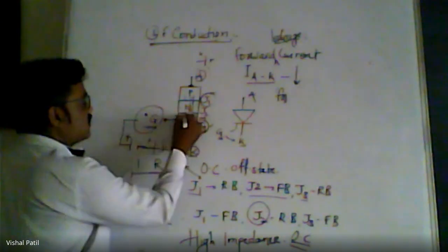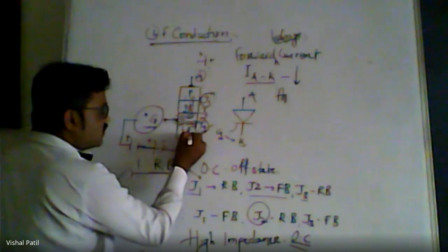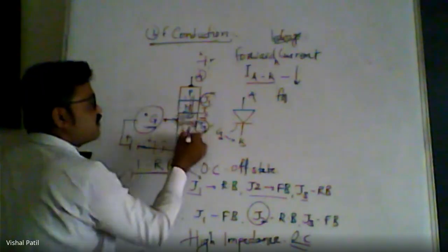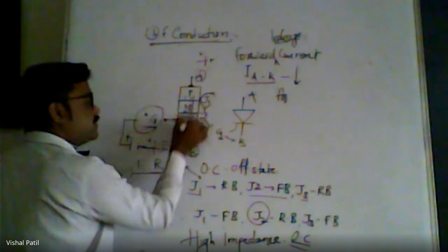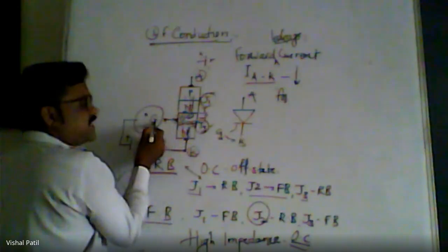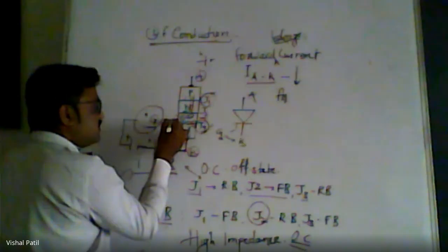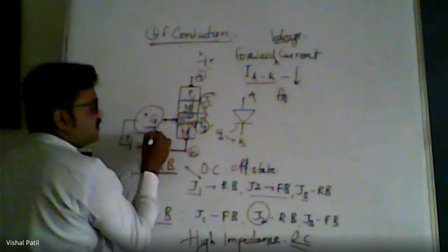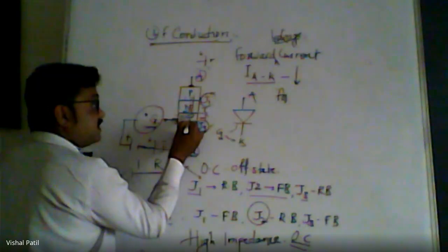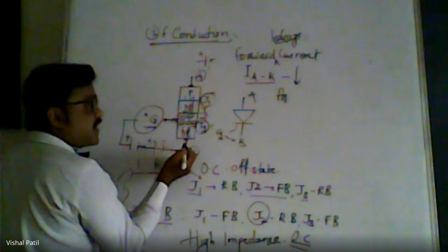The layer above and the layer below are both N type layers, and in between them there is a P type layer to which the gate is connected. When the gate is provided with positive potential, there is a current from the gate into the P layer, because of which there is an exchange of carriers.